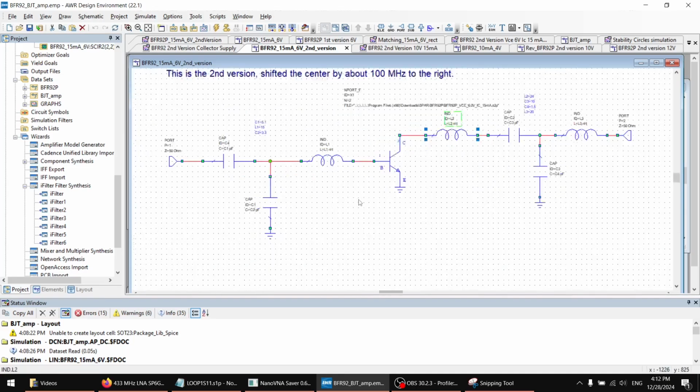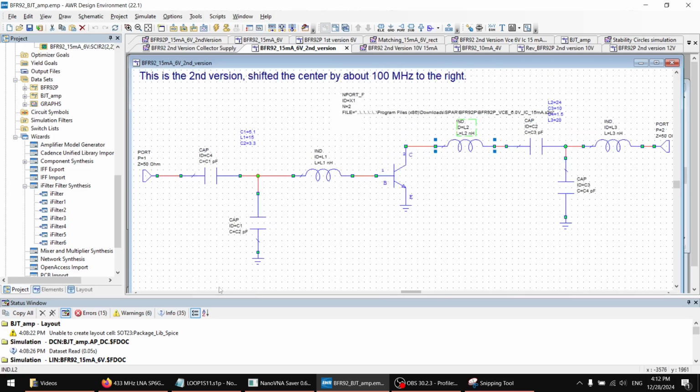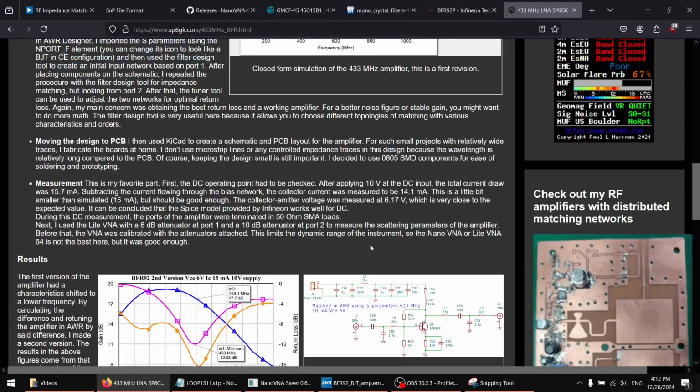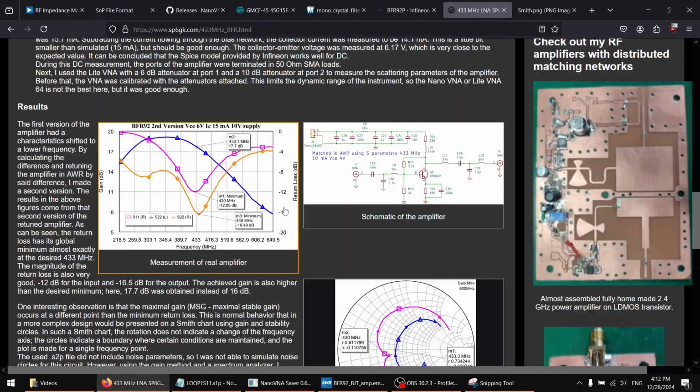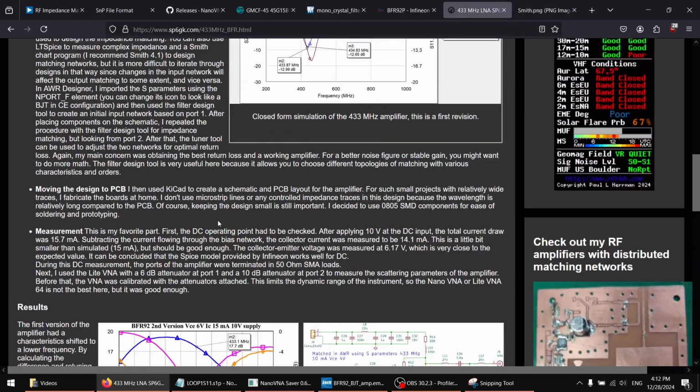So why would you want to even design something like this if you can go to Mouser, for example, and buy a pre-matched MMIC that will have higher gain and maybe be much more broadband? It's because if you are using this method, you can match exactly where your impedance will be, and because this is a tuned amplifier, it might help you with elimination of some of the